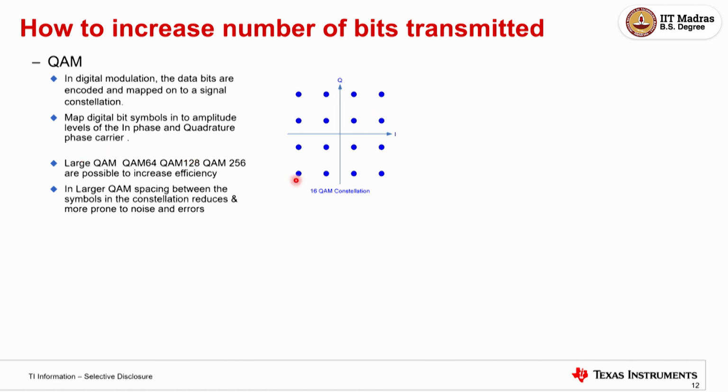That's what QAM is. So fundamentally, at least for the 5G communications, the kind of modulation they use, 256 means this is 16 by 16. That means they are actually mapping 8 bits in the same bandwidth by modulating your cos and sine by 8 different values.